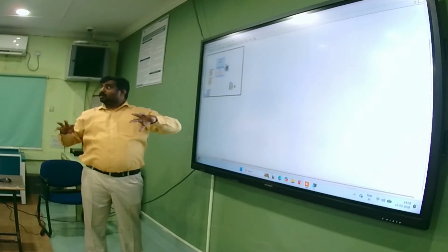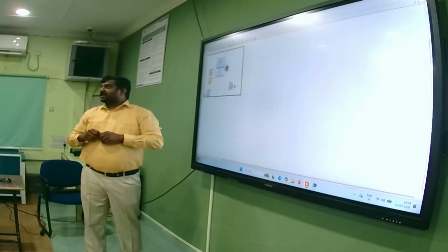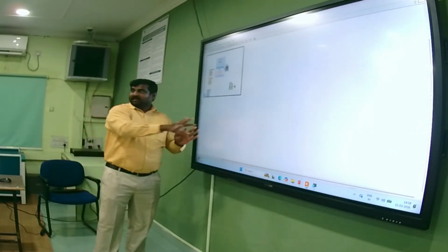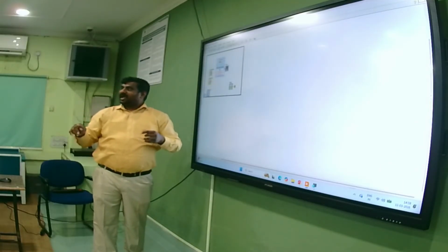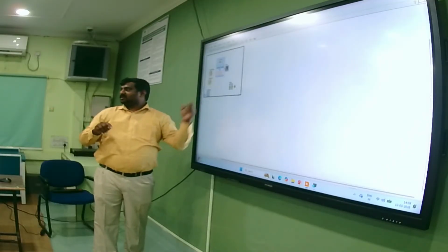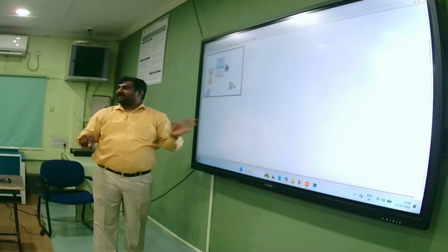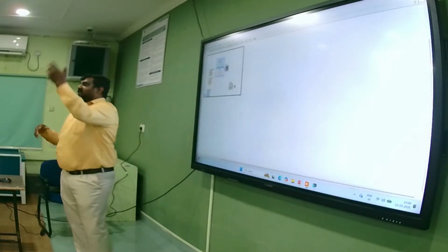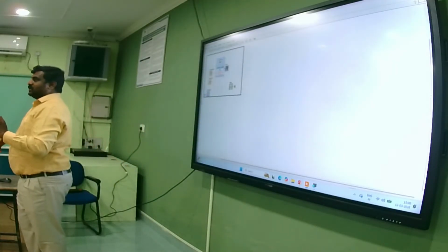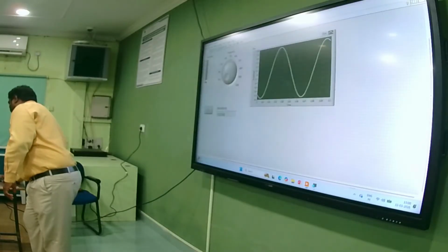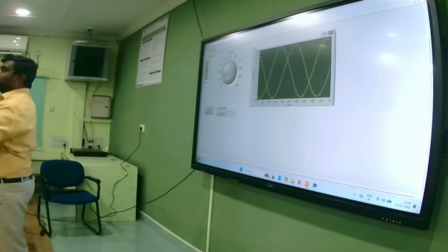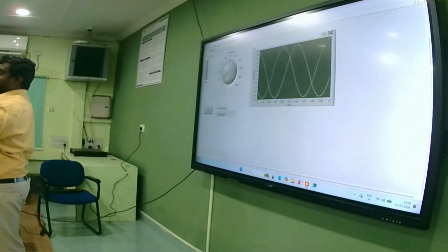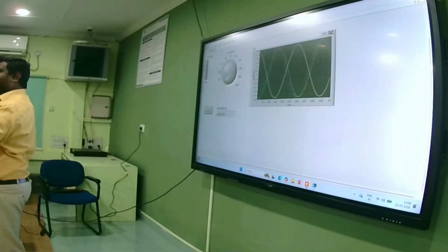But when you do run continuous, what happens is the first time the logic runs, the while loop runs n number of times. You stop the while loop, and again the logic says run again. So the while loop will run. You stop, the logic says run again. So it will keep on running. You can't stop it. So see here. In run continuous, how to stop it, I will tell you. Don't go and hit that red dot.